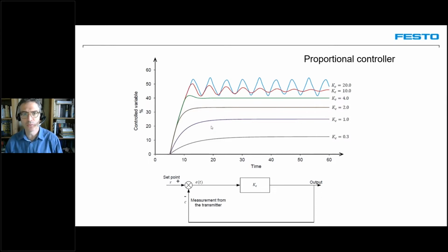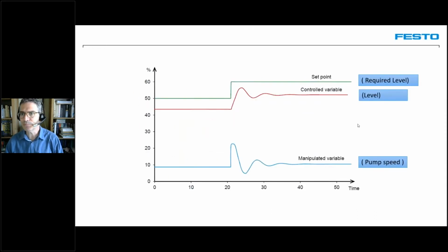Depending on the process, what might be most important is the speed of the response. In some other processes, it might be that we never want to overshoot; it can be slow, but we want it to always be in controlled mode and really close to the value, never overshooting. So depending on the process we are controlling, we will have to select the proper gain.